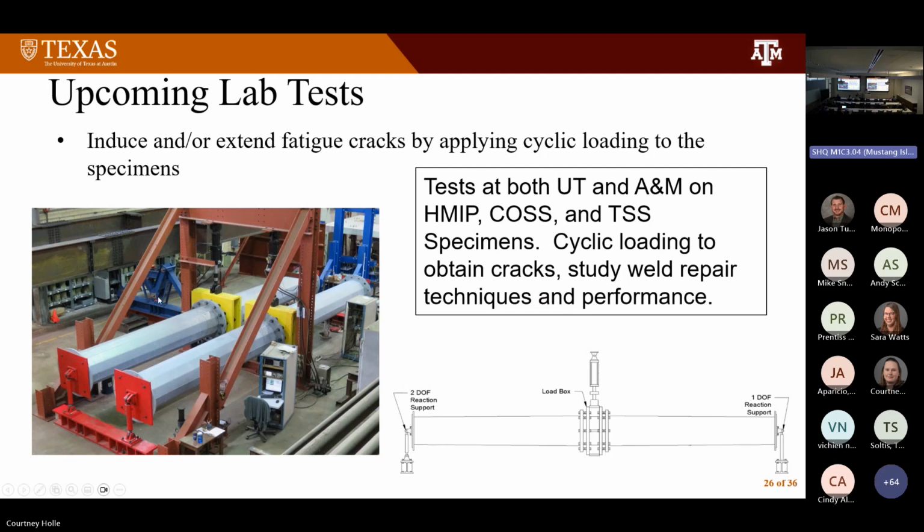When we look at this as we do these tests, it's really the top of the pole that ends up getting the damage from the cracking. What's nice is we can take a single pole, do some tests on it, see what happens, and if we want to look at repair or whatever, we can then rotate it 90 degrees. Right at mid-height of the specimen is the neutral axis of bending for the test that we've done, and the bottom is actually in compression. So it's mainly the top of the pole that takes the main damage during these tests.